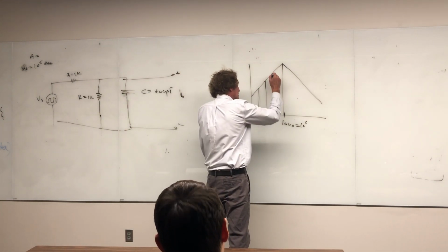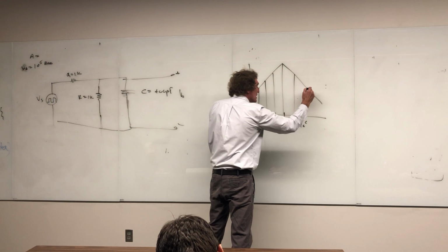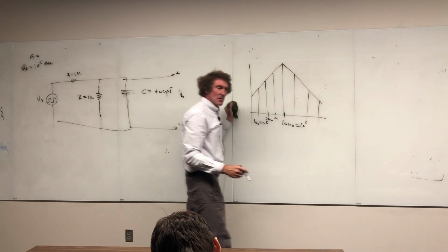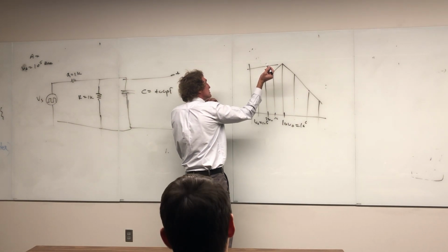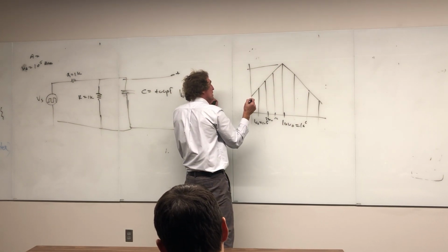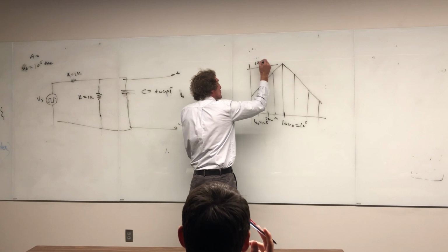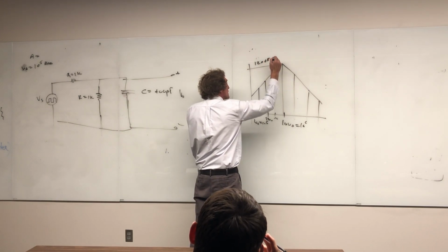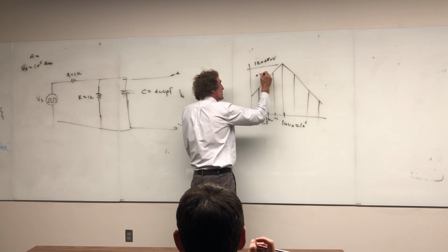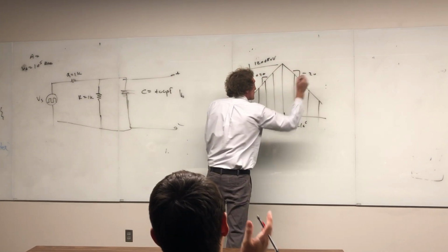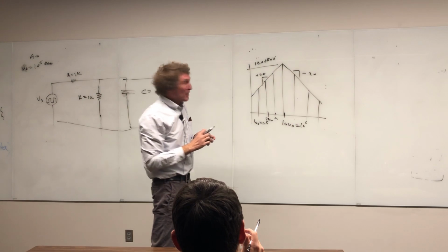He's got a bunch of spectral lines, as I can tell, right? And what does he want? So this, and what's the peak here? The peak, he doesn't give you the peak. Oh, it's 120 dB. 120 dB microvolts. And minus 20? Or plus 20, I mean? Yeah. And minus 20. Okay. That'd be minus 40. Minus 40.